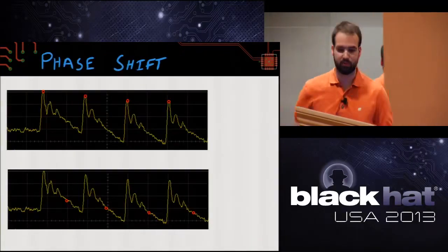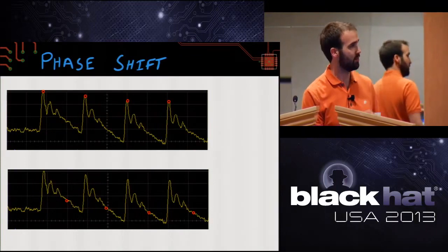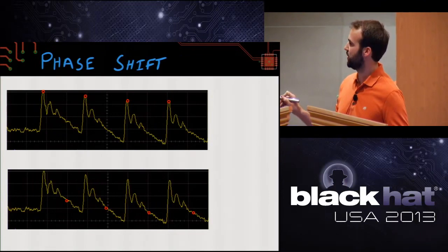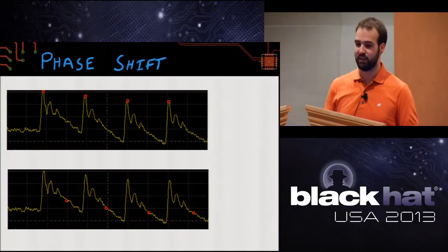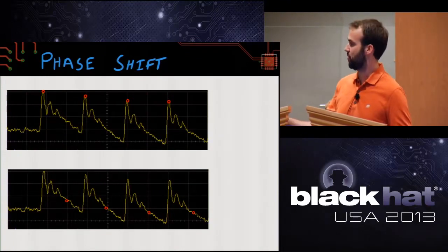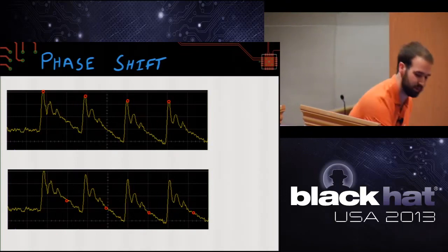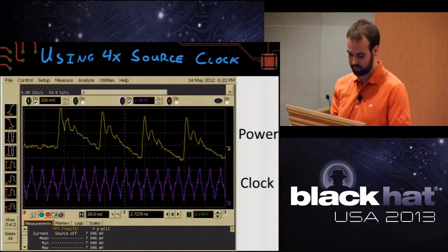The one small change when you're doing this with its sample clock is you need to be concerned about phase shift. So we can see in red, there's some sample points. So I could say, well, if I could sample here, that's really good. It may be that because of delays in the system, I actually sample at the 0 crossings and I really don't get any information, so this bottom one. So you need to be able to control when the sample occurred relative to the device clock. You also may